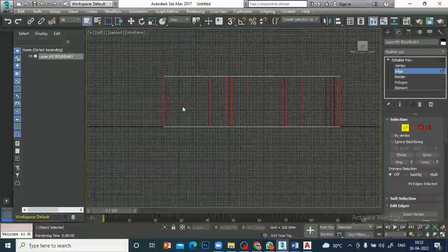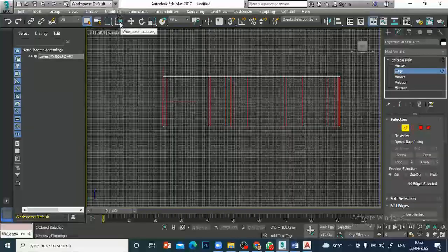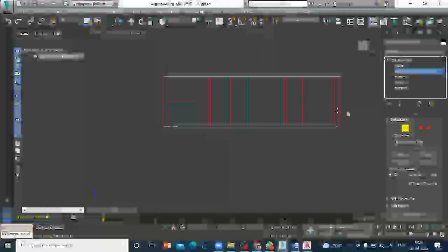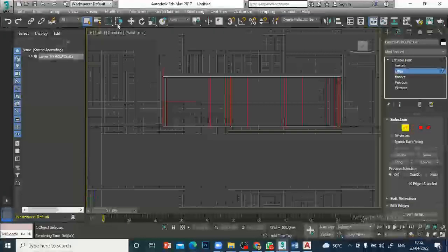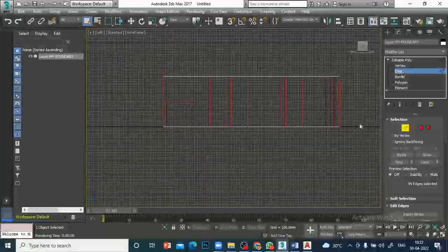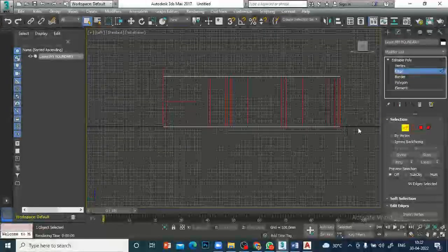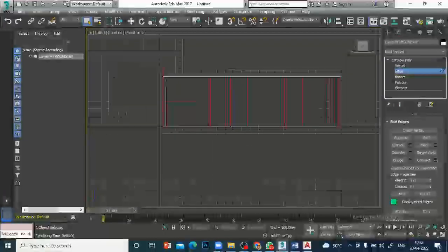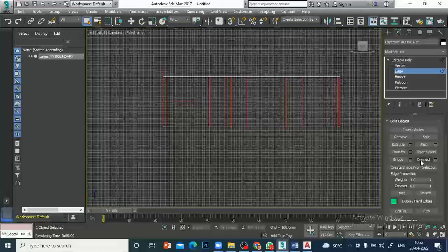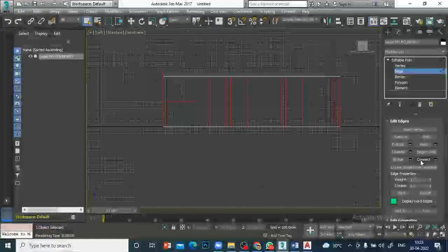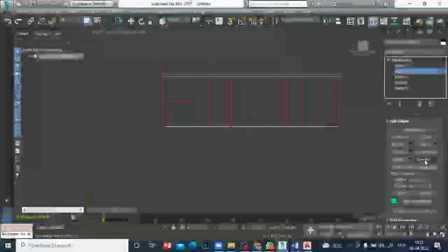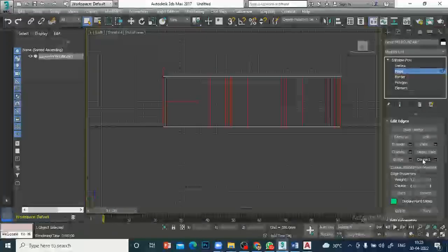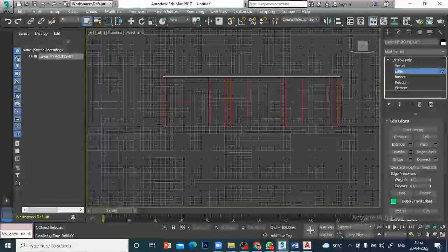You'll see the cross window will work only when the selection is here, cross window. This should be on cross window. Otherwise the cross window may not work. So I went to edge, show a cross window, and it's selected. You go down. There is an option here called connect. Next to that, there is a small box for settings. So click this connect settings. Click.